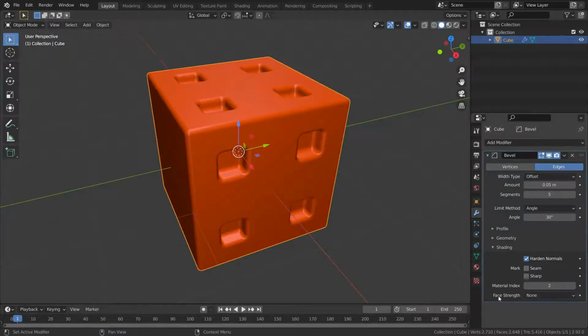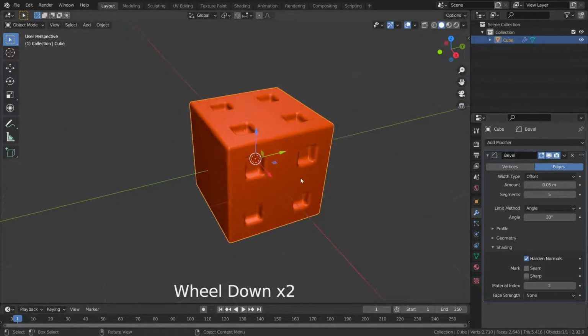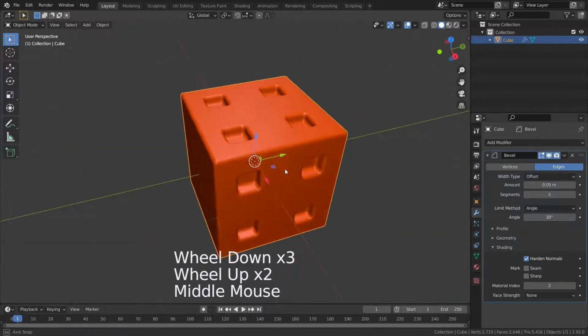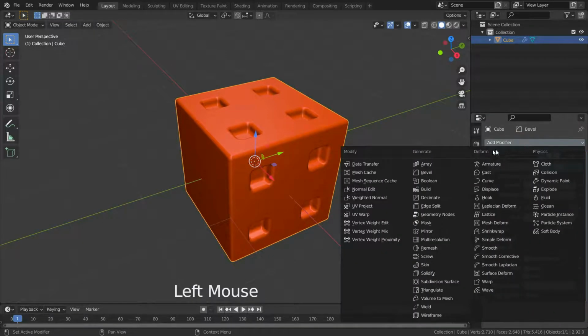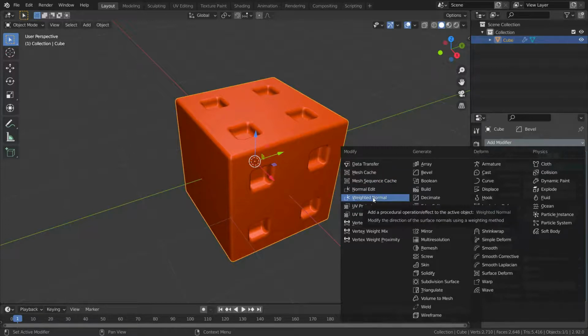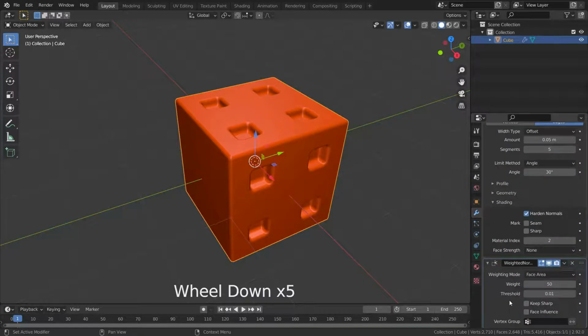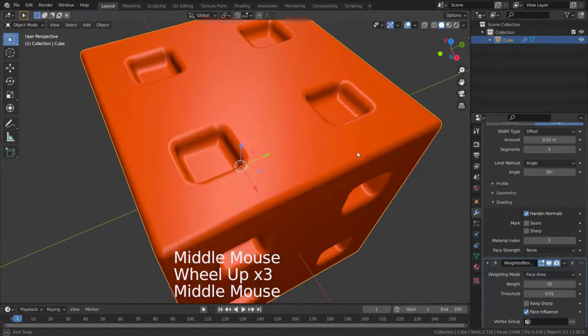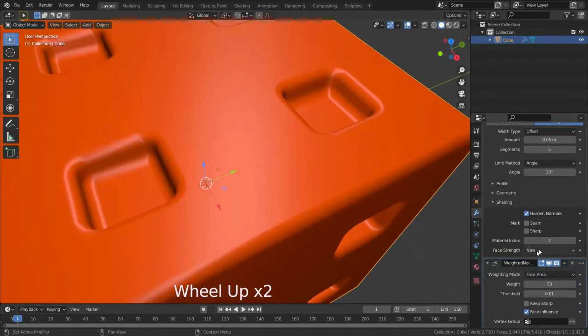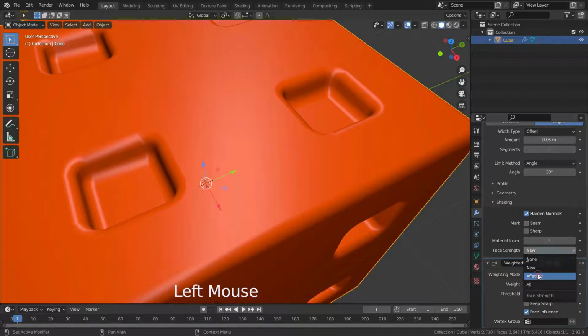Set face strength on the faces involved in the bevel, according to the mode specified here. This can be used with Weighted Normals modifier. Let's add Weighted Normals modifier. The Face Influence option should be enabled. Let's try the different face strength modes.